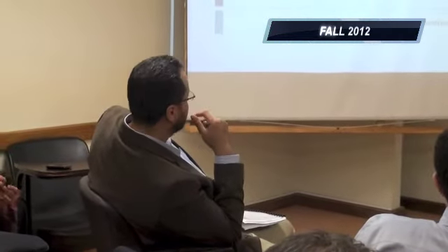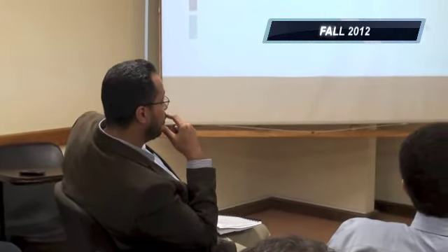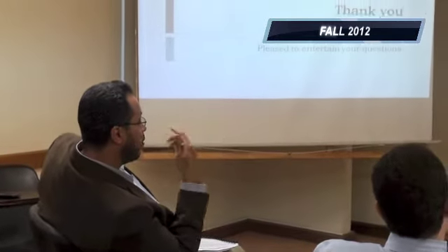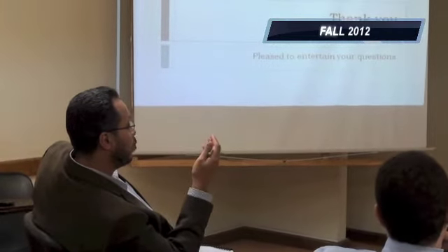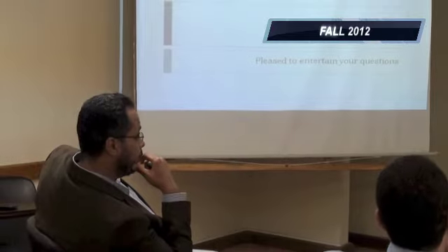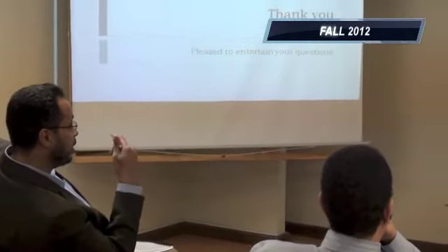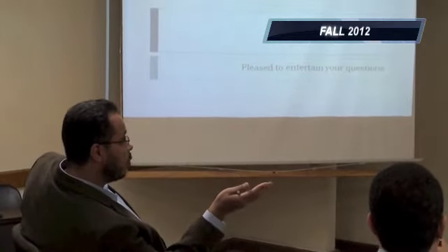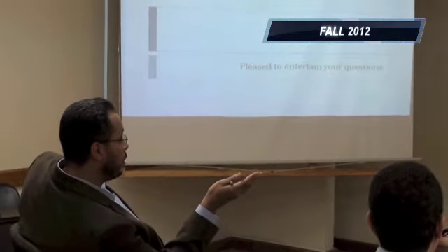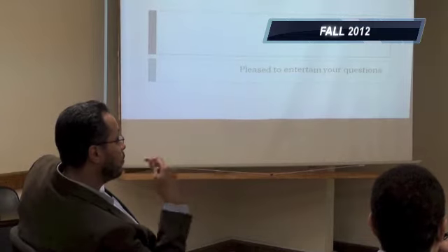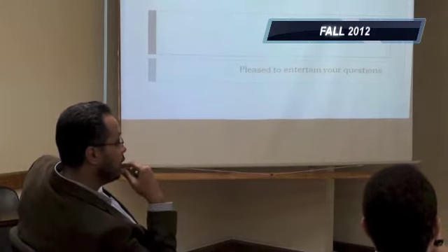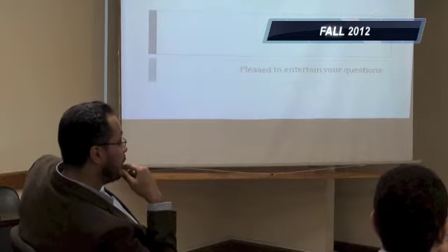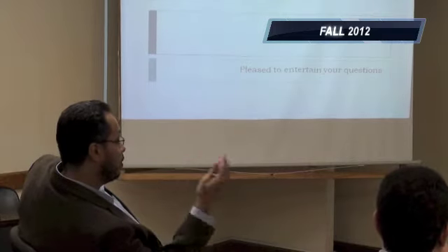And in your analysis for seismic, if you will get to that, think about the multiple support excitation as the other group indicated. Basically, when we have 2 banks of the river, you expect that the ground motion input on one side could be slightly, maybe significantly different from the other side, so that could produce relative movement between the two sides.